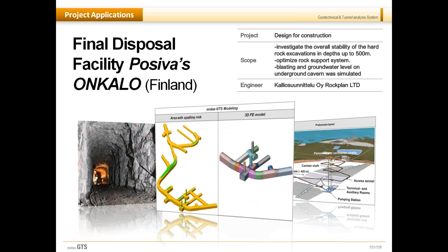A final disposal facility in Onkalo in Finland. So this is a nuclear fuel disposal that used MIDAS GTS. It was to investigate the overall stability of the hard rock excavation in depths up to 500 meters, and also to optimize the rock support system. And what was really important was the impact of the vibration due to the blasting and the groundwater level of the underground cavern that was simulated.